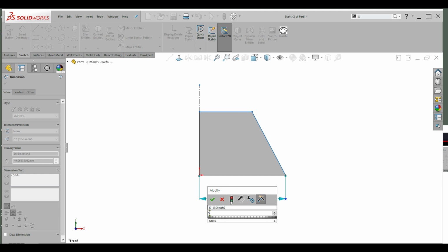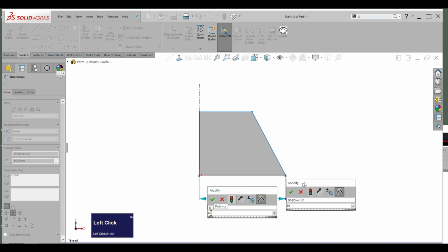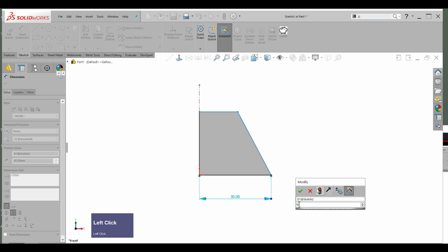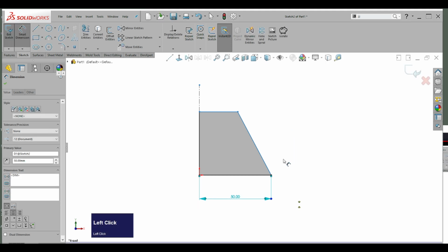Well, actually, maybe that's too small. Let's just make it 60, and then I can confirm that that's a change I want by clicking this little robot sign. That's regenerate, the regenerate button. And if I don't want it, I'll just change that and click that again, and you'll see everything updates. And once I'm happy with it, I click the OK button.